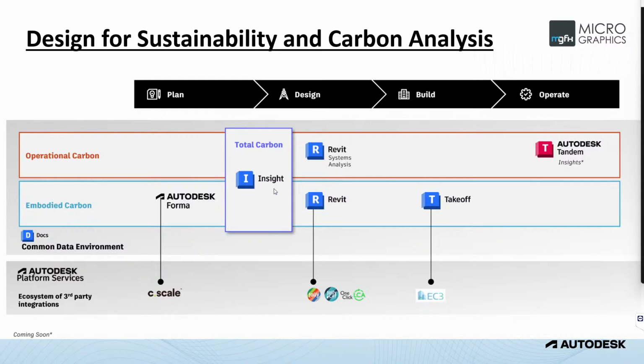Then it's built upon something that the older generation might remember as Green Building Studio. The GBXML export that you see, the GB stands for Green Building. And then Autodesk has transitioned into this Insight engine. Well, the Insight dashboard is built on top of the Green Building Studio engine. But that gives us feedback on the carbon analysis and the energy analysis in our building.